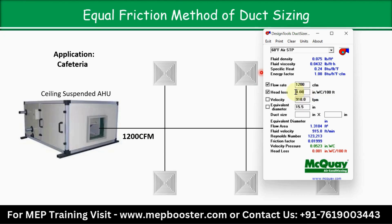Here noise is not a factor, but let's say I am designing for 0.08. As per this friction or head loss of 0.08, when I have entered these two values, flow rate and head loss, the velocity and equivalent diameter we have already got, and here we have selected the rectangular duct. Remember one more thing. Now see the duct size. In the first box, just enter the height, how much height is available. As per that, you will get the width. I am changing the unit because I want the size in millimeters. From here you can change the unit to metric. Now we'll start from the first. I am entering 100 mm height, and we have got the width 2000.